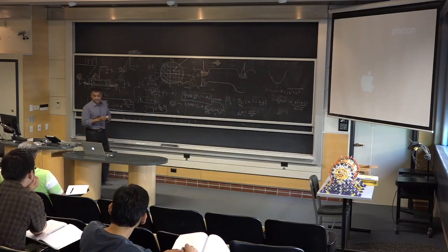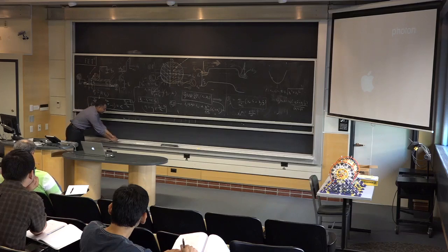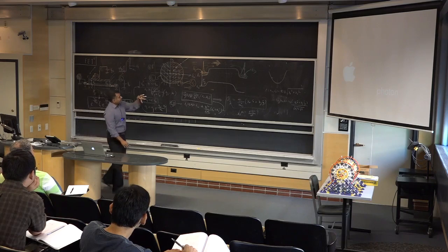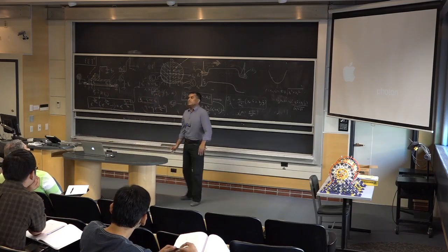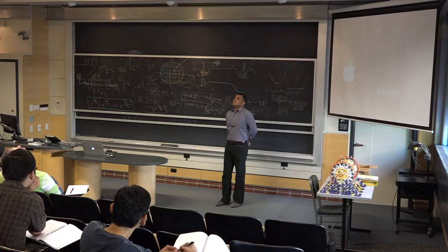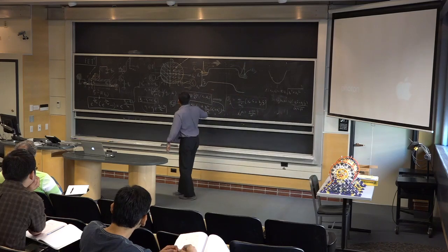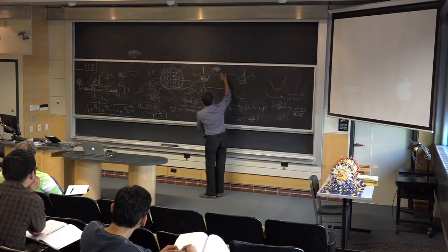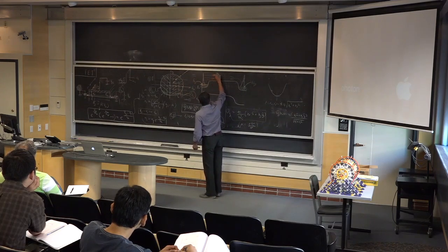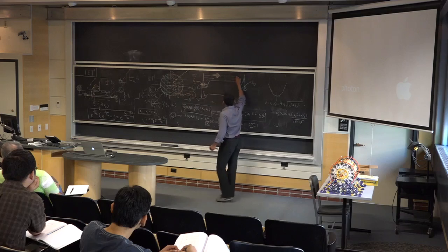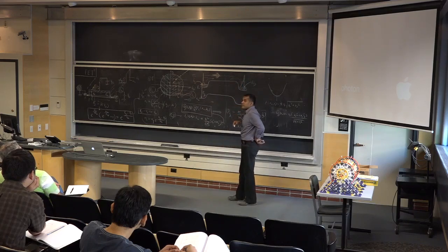Yeah. So an electron coming from the source has a specific kx and ky, and it retains that kx and ky until it reaches the drain. Correct. So the energy of that electron remains the same. Yes. So with respect to the conduction band edge, the electron energy will be the same. But on an absolute scale at the gate, the electron energy changes.